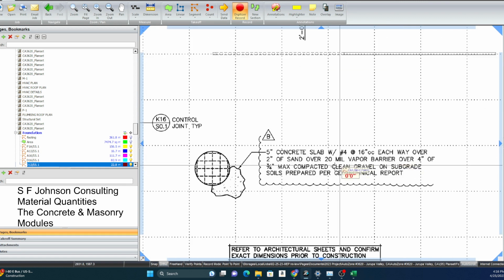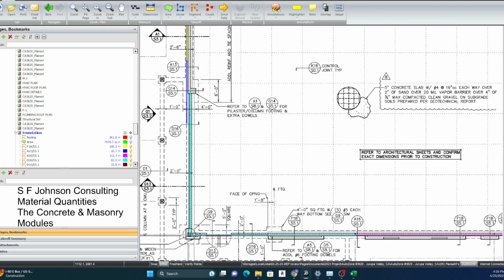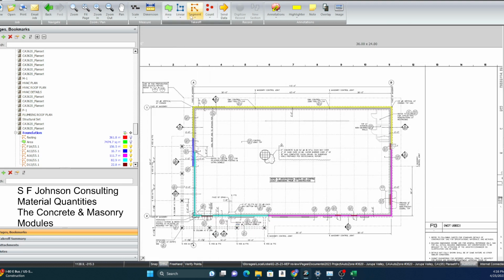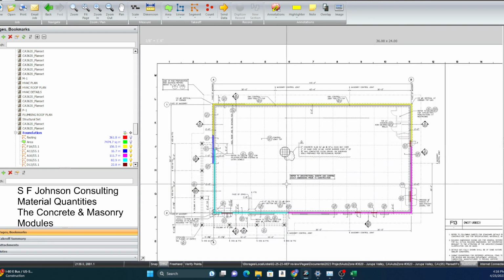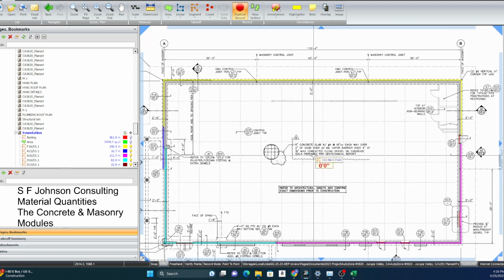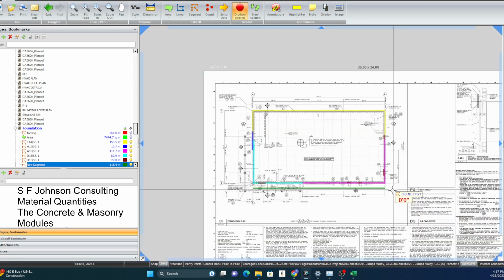Okay, and so number 4, 16-inch off center each way. So basically what you do is, so number 4 rebar, 16 inches. Might as well do that. These are the control joints, so yeah, you have to physically measure those. And so for the rebar, to be able to do that math in your head, this is 114 linear feet. Oh, let's get accurate. 115 feet.